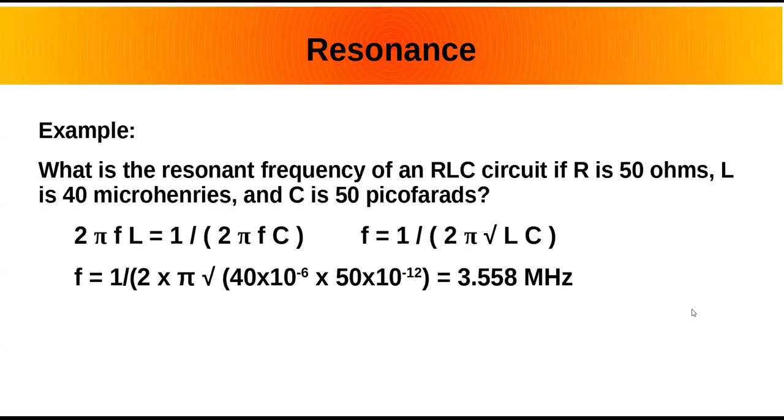So if the resistance was infinity, the frequency would be the same? Yes. Although you couldn't see much if it was infinite, unless it was a parallel circuit. Well, that's a different formula. But if it's a series circuit, then obviously you never get any current through it. And it requires a little bit of current in order to have resonance, because resonance is just the energy that gets stored in the magnetic field and the capacitive field.